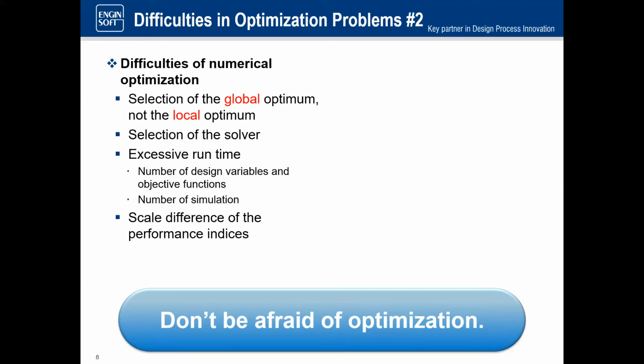So one of the things that you want to check is that the model is performing very smoothly. Things like contacts should be smooth, which speaks to the resolution of the contact itself. And you just want to check to make sure that everything has gradual transitions, as much as possible.